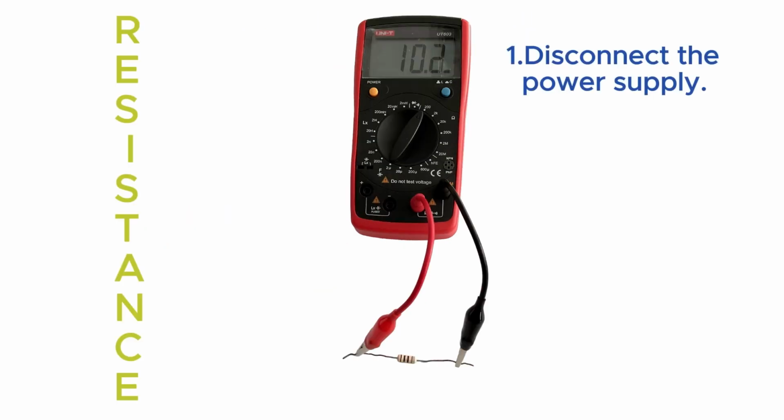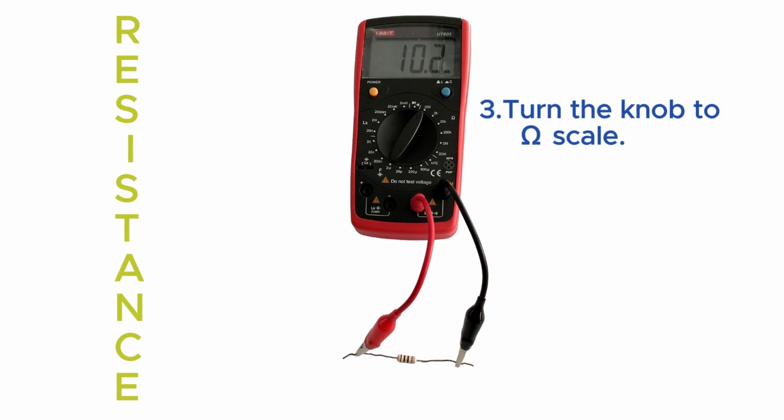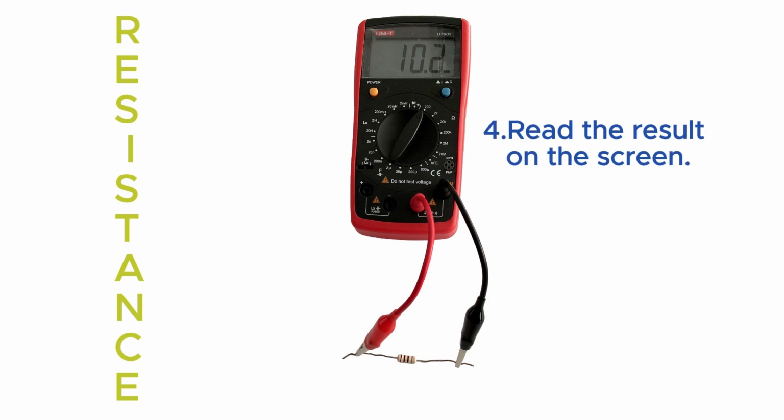Resistance. 1. Disconnect the power supply. 2. Connect the red probe to the omega slot and the black probe to the COM slot, as shown in Figure 12.3. 3. Turn the knob to the omega scale. 4. Read the result on the screen.